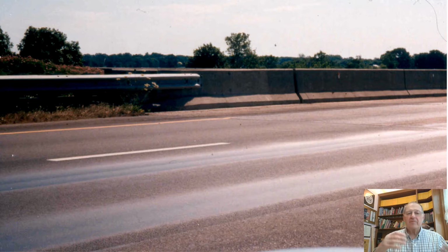So if we put too much asphalt binder, and that would be more like an accident, say a plant calibration problem or something like that, we will end up with excess asphalt binder, rutting, flushing, and bleeding. There's no washboarding on this, which was one of the other things on the list. You might get that in an urban environment near a stop sign or something like that.